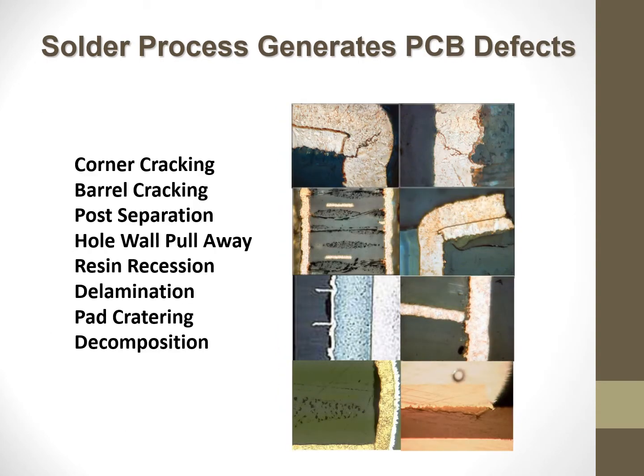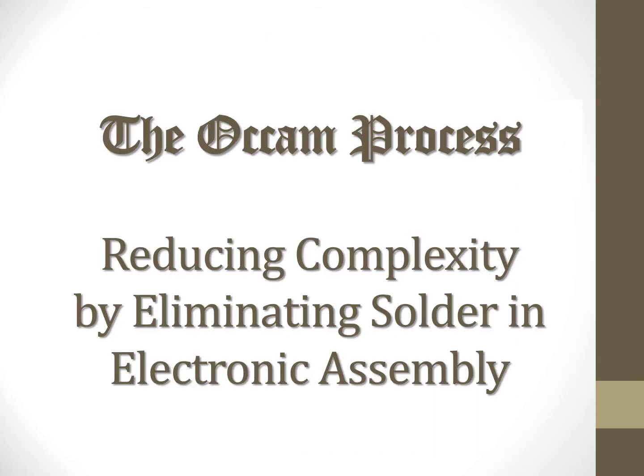Moreover, the solder process generates prospective defects in the printed circuit boards as well, in terms of corner cracking, barrel cracking, delamination, pad cratering, and with the advent of lead-free solder, even the decomposition of the polymers used in the manufacturing of the printed circuit boards can be problematic.